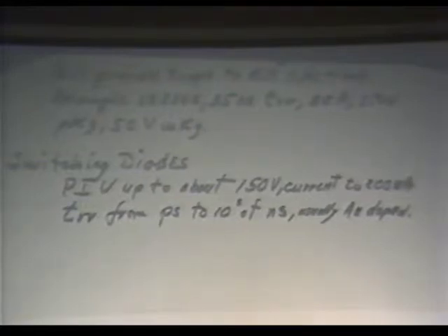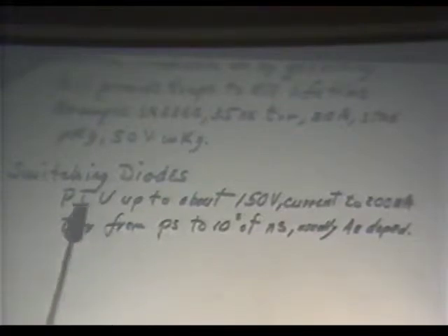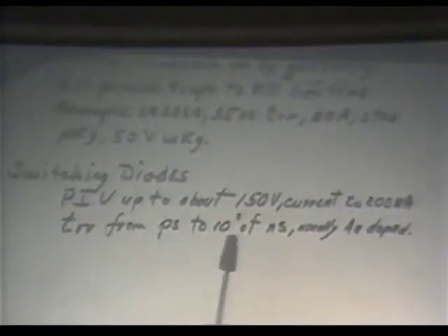That's hearsay. I never built one. And the people that originally were using platinum wouldn't tell me they were using platinum. I found it out by accident later. Anyhow, switching diodes as a class, pretty much I think at 150 volts you could chop that off, and that's arbitrary on my part. If you want to say 100, say it. If you want to say 200, say it. But I don't think I'd go beyond tens of nanoseconds in terms of recovery time to fit in that class.